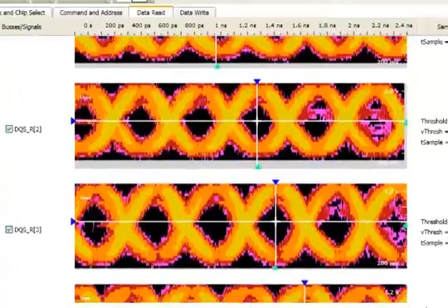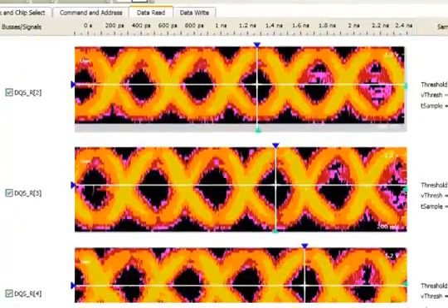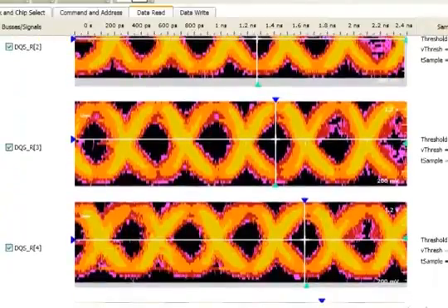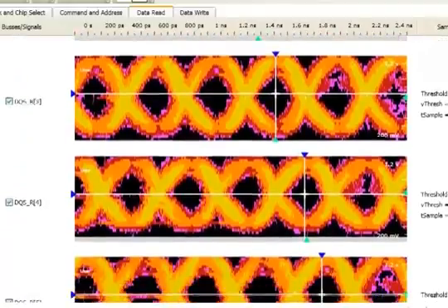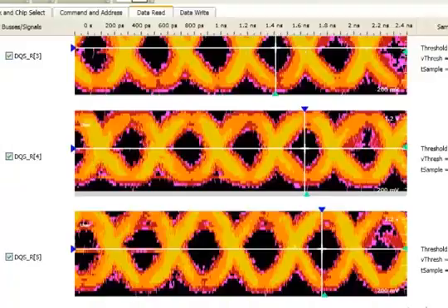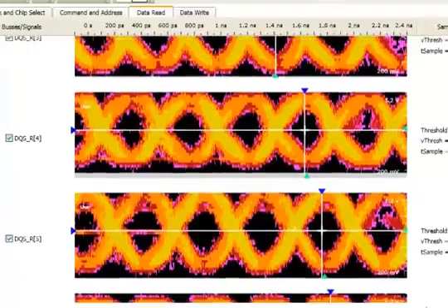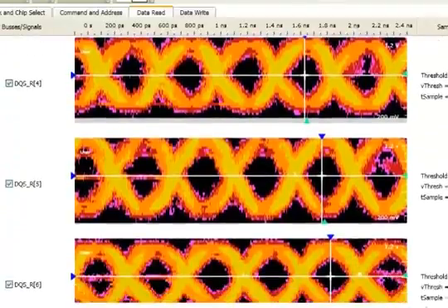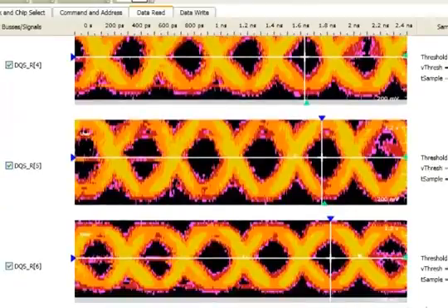Since the data is driven from the strobes, this makes sense. What we really would want to look at with our scope is the behavior of the strobe from the DRAM associated with byte lane 1 and byte lane 2, as they have the smallest eyes.